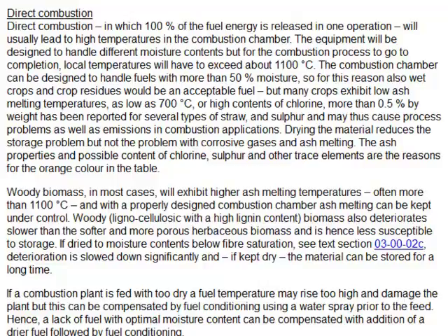So, typically, direct combustion needs a fuel that has a sufficiently high heating value to provide a high temperature. But on the other hand, it's easiest to run a direct combustion process if the fuel ash does not melt to too high an extent.